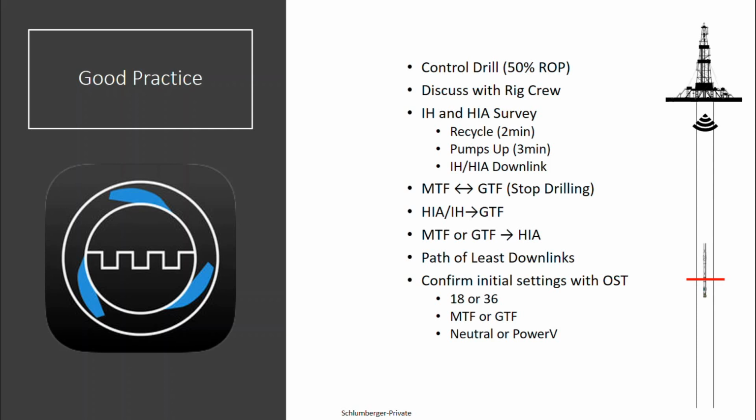Another common question is if you're going from magnetic to gravity or vice versa, whenever you send that initial downlink to switch, it will keep your tool face. So it is not recommended to drill ahead while sending that, because depending on your orientation, it could steer the direct opposite way that you desire. So just knock your ROP back to like 2 foot an hour. That way you're not making any hole. Change it from whatever tool face you want, and then send your desired tool face.